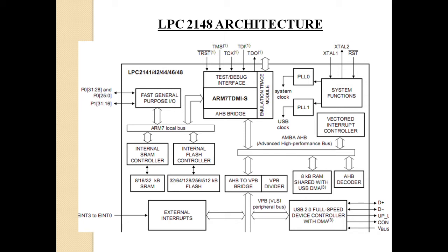Through that transparent window, ultraviolet rays will be taken to the actual silicon chip sitting inside the EPROM. If you are seeing the old 8085 kit, there will be an IC where the company name will be pasted, say VI Microsystems. One sticker will be there, and that sticker will be pasted on the EPROM. Why is that pasted? In order to cover that transparent surface.